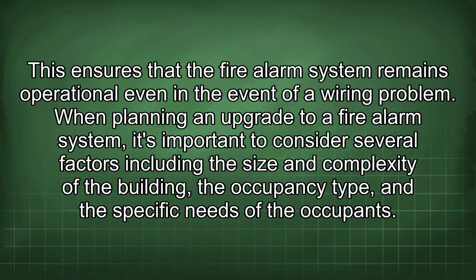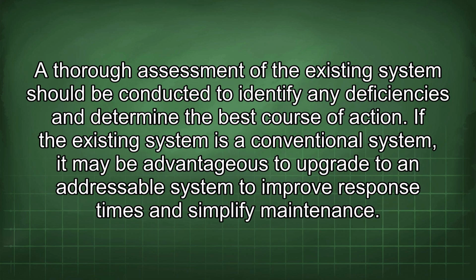When planning an upgrade to a fire alarm system, it's important to consider several factors including the size and complexity of the building, the occupancy type, and the specific needs of the occupants. A thorough assessment of the existing system should be conducted to identify any deficiencies and determine the best course of action. If the existing system is a conventional system, it may be advantageous to upgrade to an addressable system to improve response times and simplify maintenance.